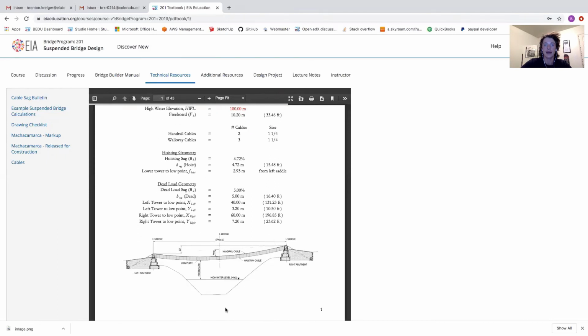Notice how schematics are used for context, showing the reviewer what part and aspect of the bridge you are referring to. Also, make sure your information in the calculation package is standalone. Don't refer to previous reports unless otherwise noted by reviewers. They must be able to find all information within this document. Finally, some of these resources may have more advanced calculations, so always use the review call guides and checklists in the Bridge Binder appendices.